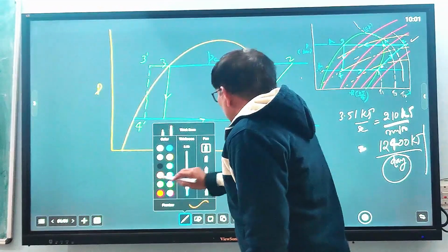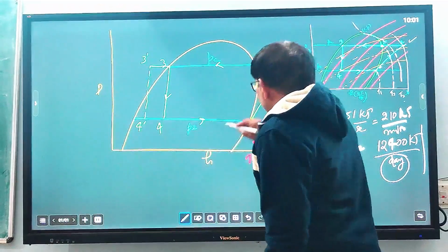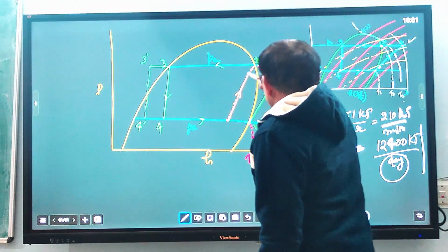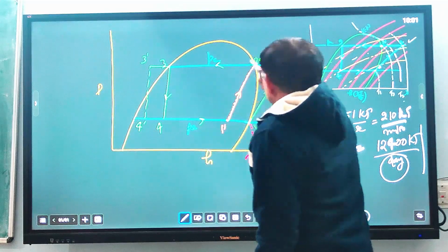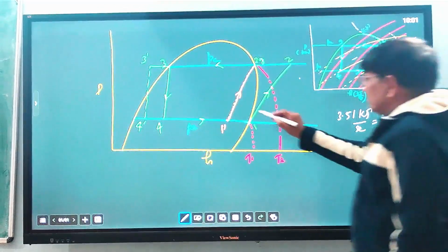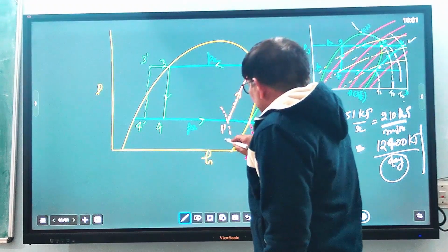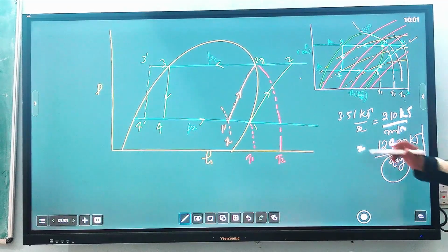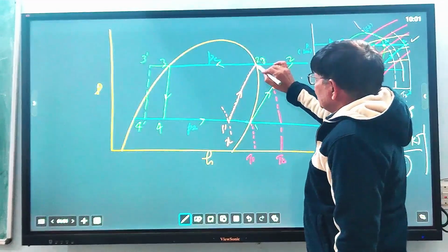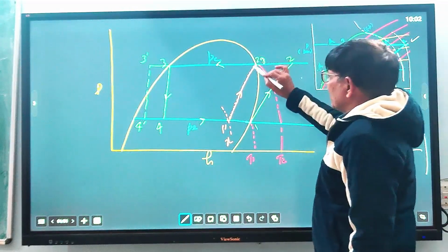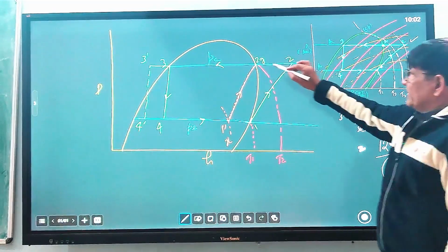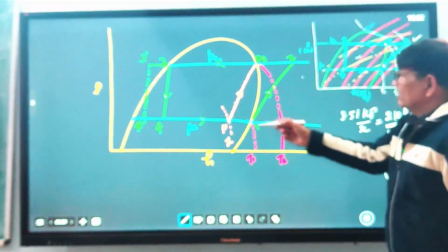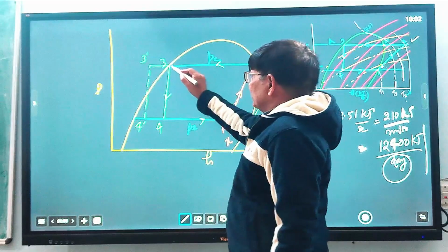In the second situation, vapor enters the compressor at this condition, 1 dash. This means there is a mixture of vapor and refrigerant, that is, the refrigerant has some quality with moisture content, and after compression it is just at the saturation stage, a saturated vapor. After compression, the refrigerant becomes fully saturated. This is another condition, and further undercooling takes place. Are you with me up to this point?